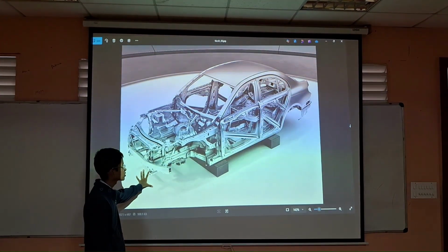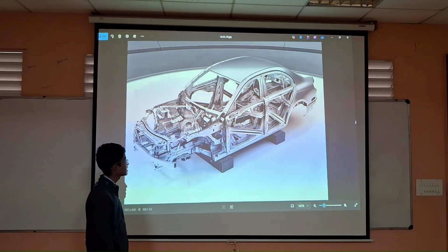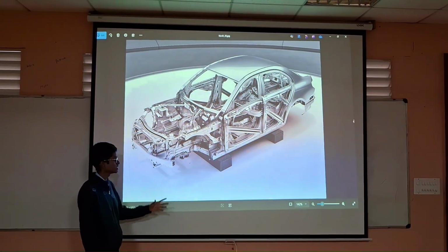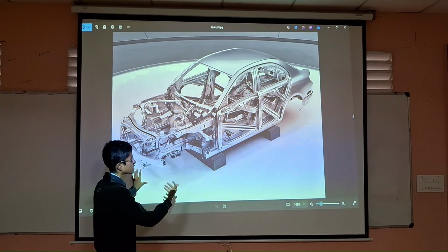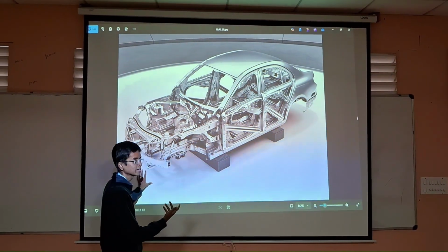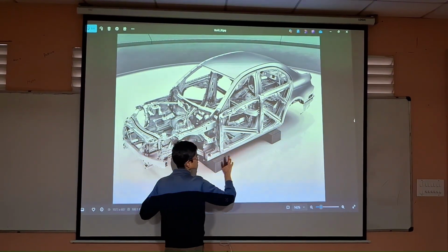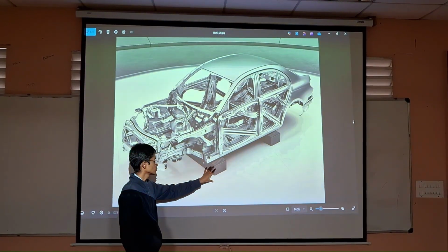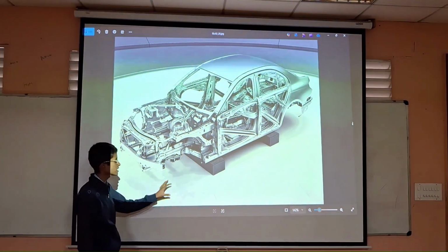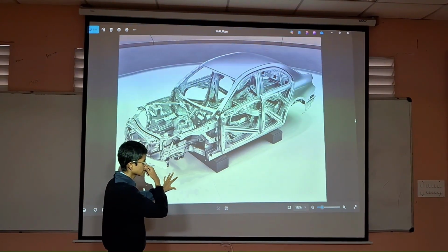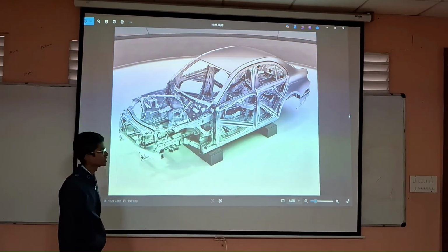Due to its low ground clearance, it is difficult to maneuver a monocoque chassis vehicle off-road. Its other main disadvantage is serviceability. Unlike body on frame, where we can jack the vehicle at any part of the chassis, monocoque has specific hard points, and the jacks should be placed on those specified hard points. If improperly jacked, the bottom rails can bend, thereby damaging the whole body.